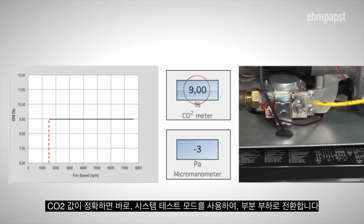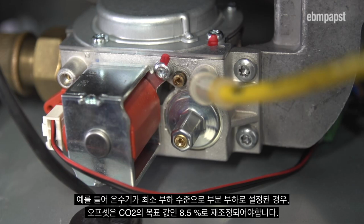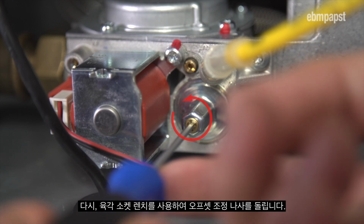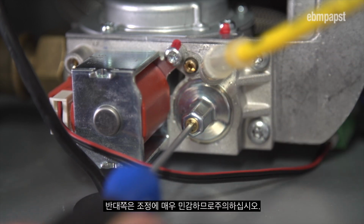As soon as the CO2 value is correct, use the system test mode to switch to part load. For example, with the water heater set to part load with a minimum load level, the offset has to be readjusted to the target value of 8.5% CO2. Again, use a hexagon socket wrench to turn the offset adjustment screw. Take care, as the offset is very sensitive to adjustment.